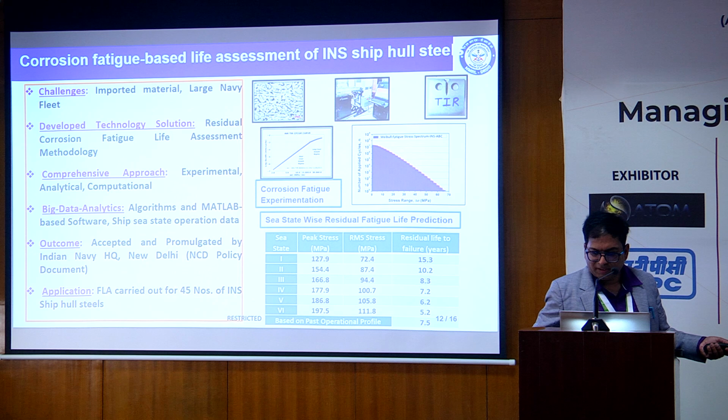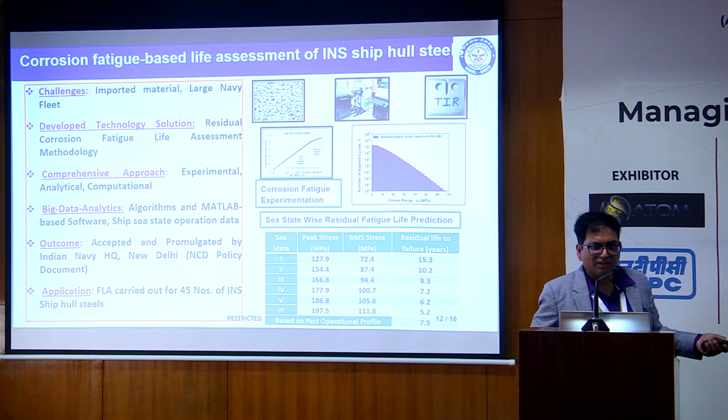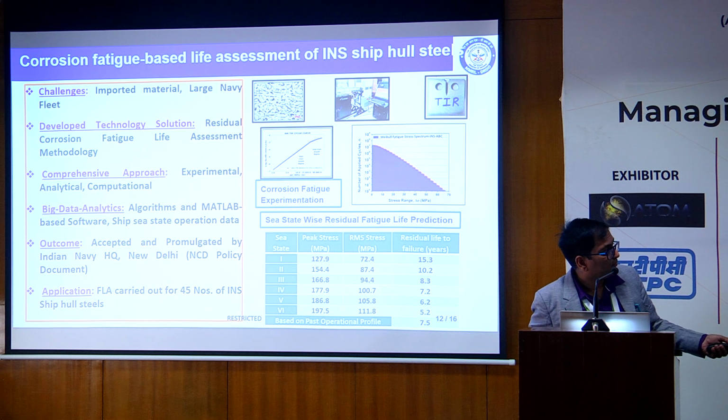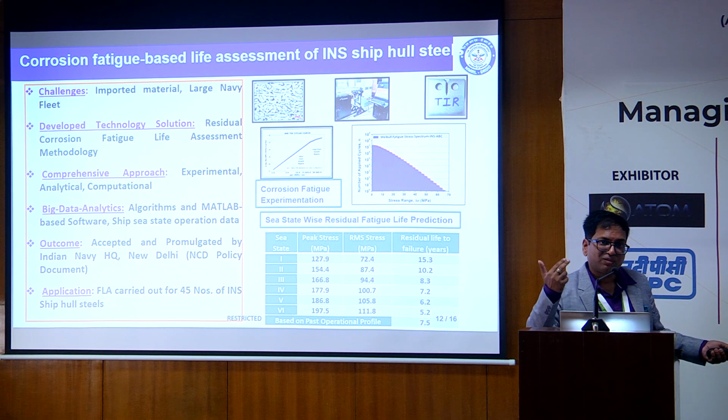So we incorporate this history and try to calculate the peak stresses, and then from the spectrum, Weibull-based spectrum modeling of this sea state, include that in our algorithms and calculate the fatigue life based on the operational profile. And on the right side you can see the residual life if the ship has to operate in sea state 1, 2, 3.